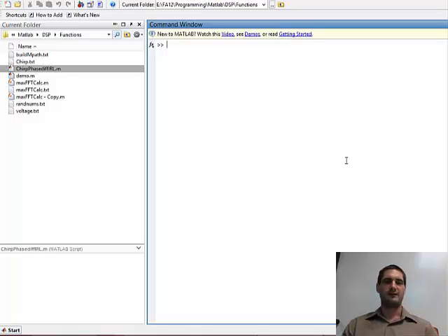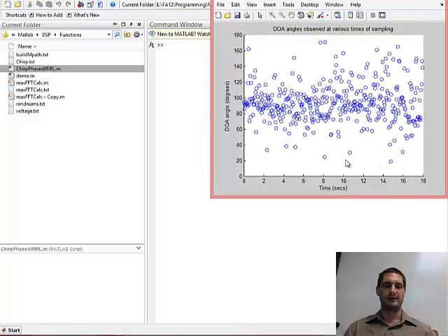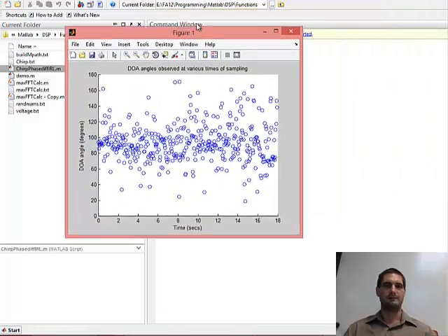Once we had the samples taken, we saved them in text file format, as shown earlier in Signal Express, and we wrote a MATLAB script that will load up columns of these text files and perform the chirp Z transform on these samples. I'm about to show a little demonstration of some of the scripts that we have written. This script will load some of the samples taken and show a graph depicting the direction of polarizable angles as we've moved around the receiving system. Quite a few samples are taken, so sometimes it takes a while, but this one is done.